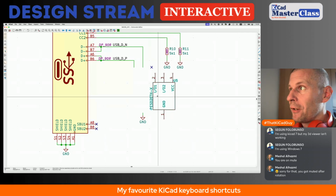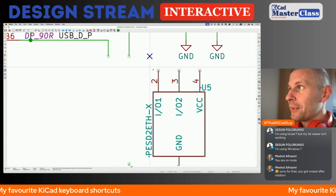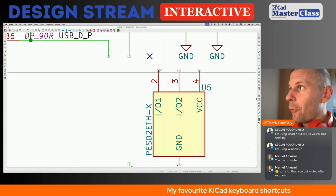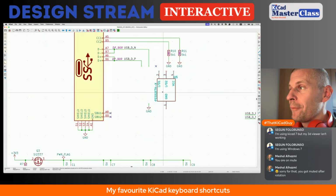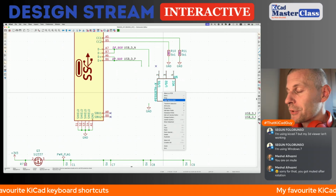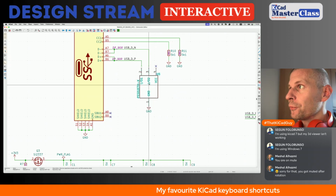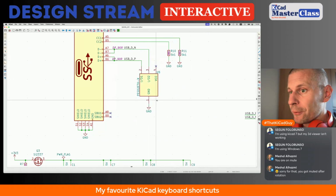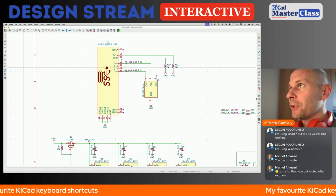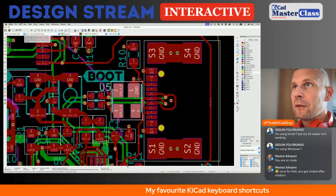This is the danger. You place the symbol off grid, and you can't connect the port. How to solve it? Go to the context menu, right mouse click, and align items to grid, and KiCad automatically moves it to the grid. So this is what I said, and I continued in the PCB editor.